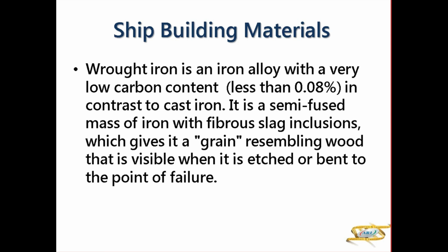So it is semi-fused mass of iron with slag inclusions, and the grain resembles wood that is visible, which is edged or bent to the point of failure. So if you cut it, you can see that grains are visible there in wrought iron.